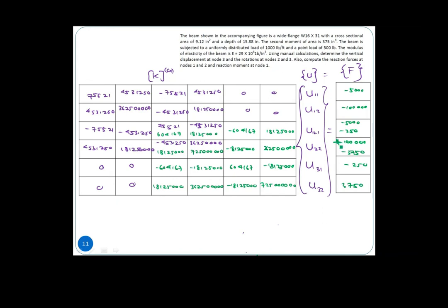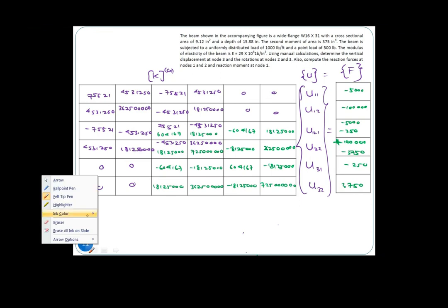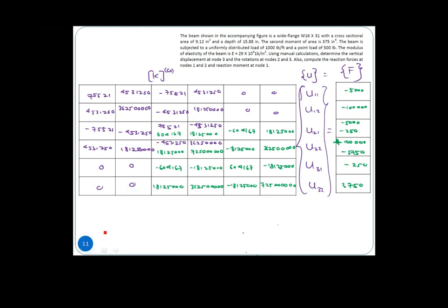All right, so again, on the boundary, actually we do not really need to compile the entire stiffness matrix. If you apply boundary conditions, we know, as I mentioned to you, that u11 equals u12 equals 0, and u21 also equals 0, right?